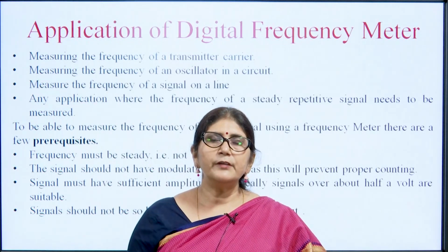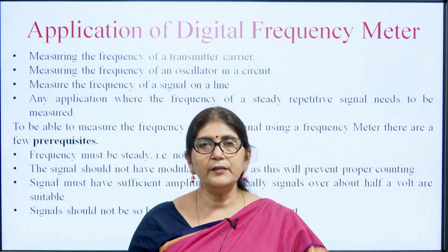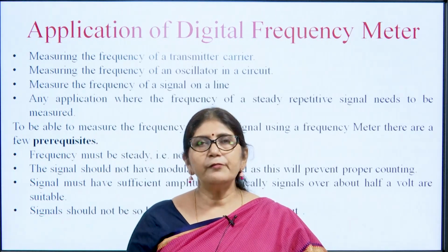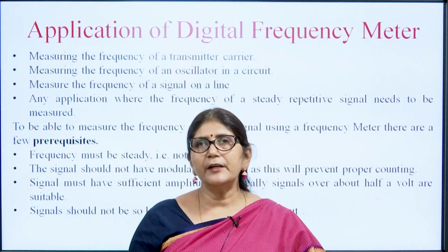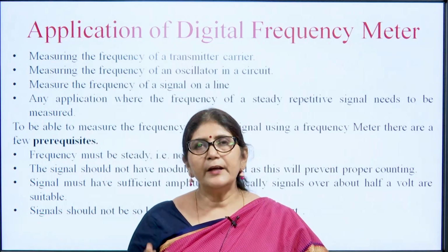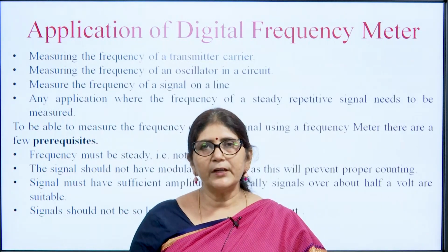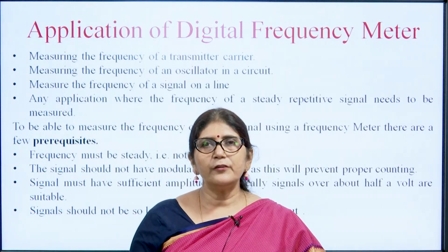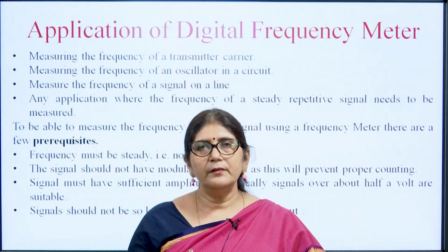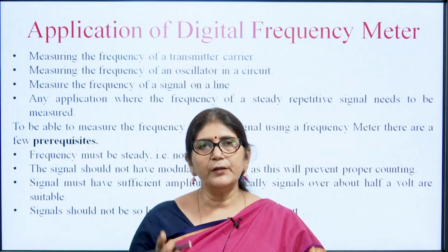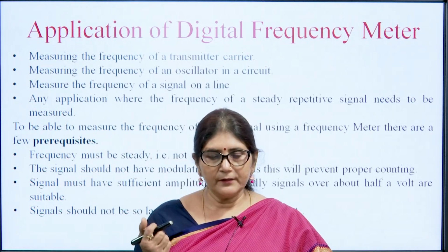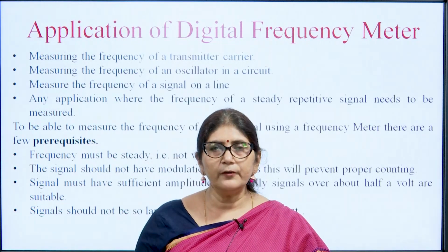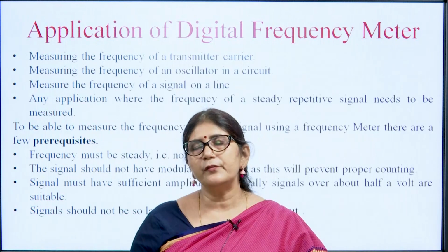Then that signal should have sufficient amplitude, meaning it should operate the digital frequency meter. Suppose if the amplitude is very low, then we can't measure the frequency, and if the amplitude is very high, then again we have a problem measuring the frequency. So, it should be in the range of a minimum of half volt, and the signal should not be very large, so that it does not overload the input.